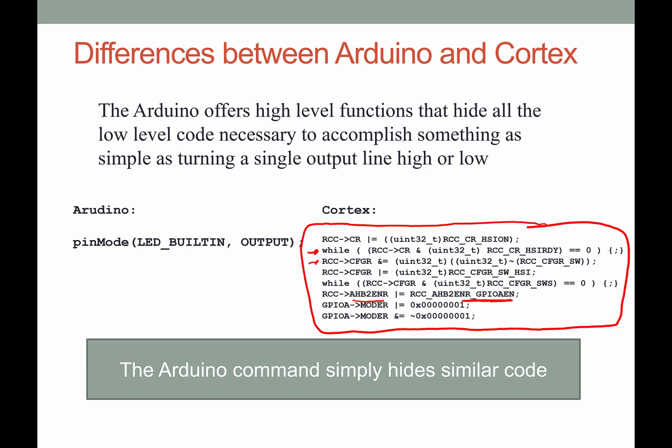One thing you might remember: in the startup files we have a bit sequence, and that bit sequence is encoded to turn the GPIO port A on. You see that it's exclusive ORed here, as we talked about. So what you're basically doing is saying, I'm going to exclusive OR the enable register with what would enable the GPIO port A.